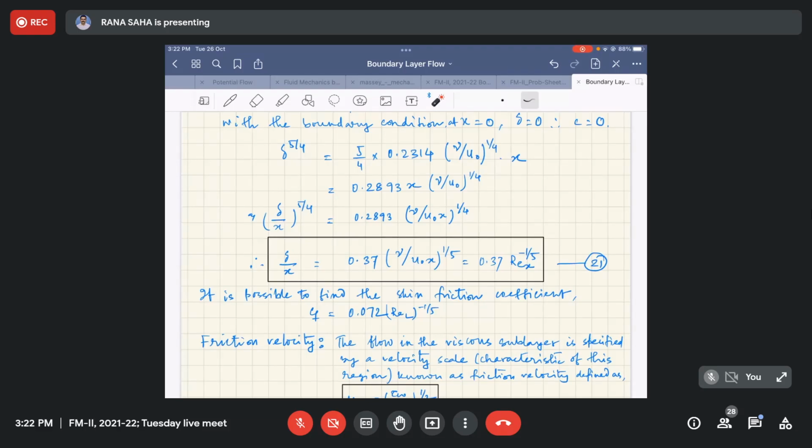Okay, so the difference here is you are handling a turbulent boundary layer over flat plate, and you are using this tau W expression, instead of using your Newton's law of viscosity, which is basically applicable for laminar flow or parallel flow.